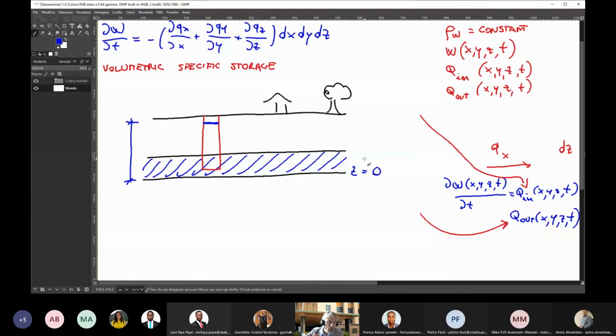Of course, you can select whatever horizontal plane you wish. So let's suppose that the aquifer has the lower level that is horizontal, and we can take it. And then we say that this is the hydraulic head. The level of water in the well with respect to a horizontal plane is the hydraulic head, okay?